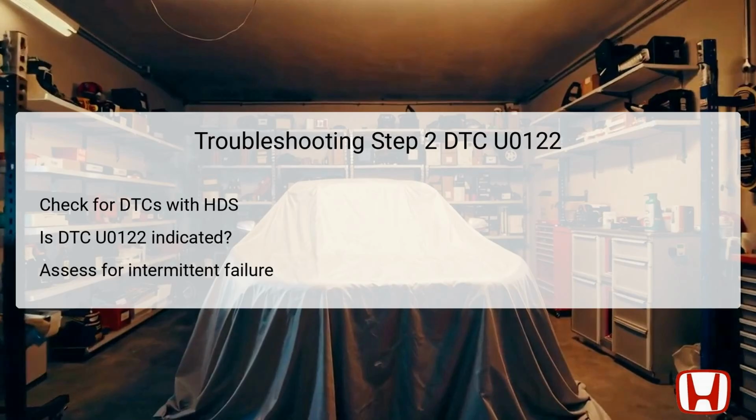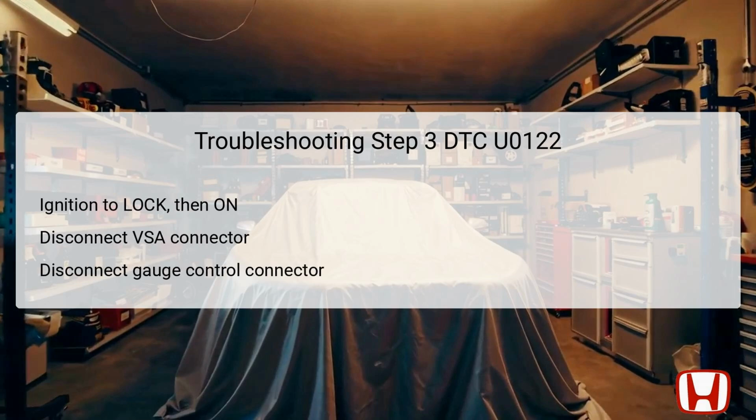It's important for technicians to consider the possibility of loose connections or faults that may not be apparent during a single diagnostic session. Hence, thorough follow-ups should be executed regardless of the outcome of this step. Continuing the troubleshooting process, the technician will once again switch the ignition to lock, followed by turning it back to the on position. This is performed to reinitialize the system before making any physical adjustments.